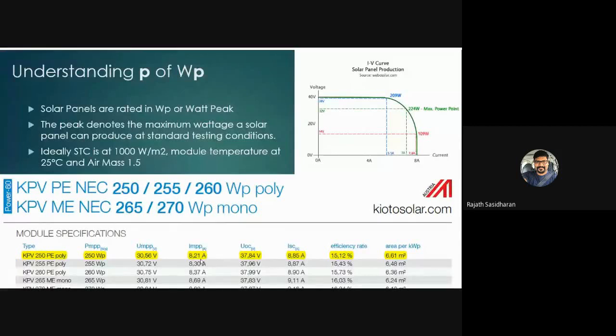So you see it's 37.84. I have highlighted one line here at the bottom. It's 37.84 volts, right? Then the short circuit current is 8.85. So these are the two preliminary factors. Next is understanding what the maximum power point is. When you have a closed circuit photovoltaic system under testing, you will get something called the voltage at maximum power point. As we all know, in a short circuit system, the voltage drops as the current starts getting out of the circuit, right?